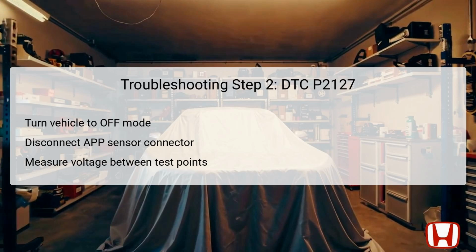If the voltage is correct, the system indicates proper operation of the voltage supply line leading to the sensor, allowing you to proceed to the subsequent troubleshooting steps. If not, address potential issues in the wiring or connections.